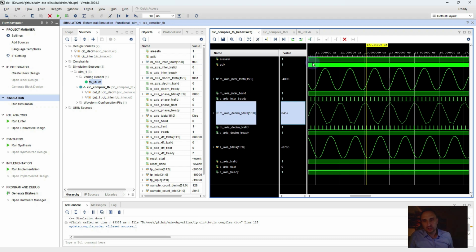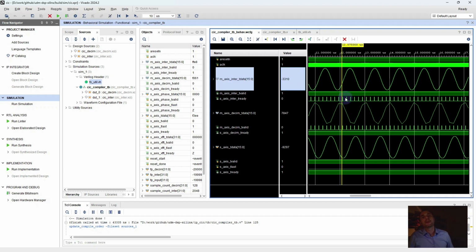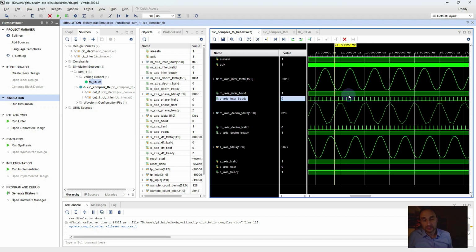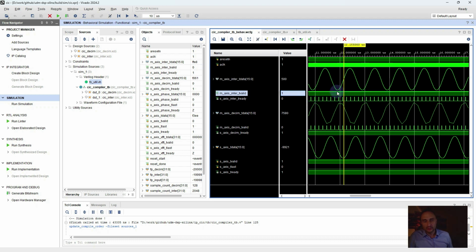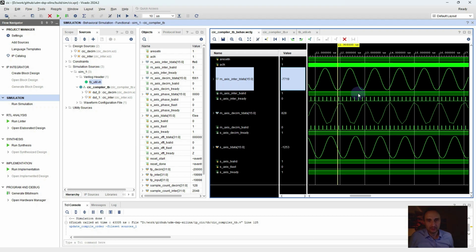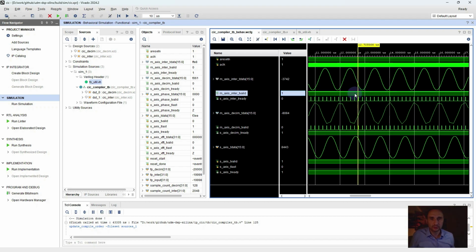So in the test bench, I wrote decimator output to interpolator input, and therefore here I am reproducing the input signal. Of course, since the input signal for the interpolator has a sample frequency 16 times less than the sample frequency, the output of the interpolator is provided, as can be seen here, every 100 megahertz sample clock, since it's an up conversion.